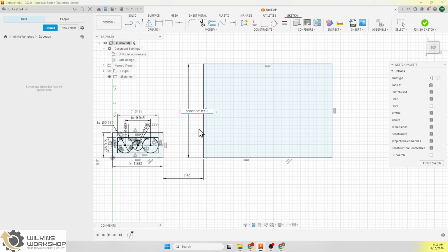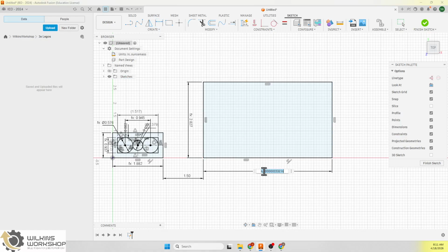All right, how tall should this be? Well, this should be Lego base times 3 minus 2 kerf. So that's how tall a 3 by should be. And then we go to this one. And this should be Lego base times 4 minus 2 kerf. So again, you only have air gaps on the outsides of the part. So that's why we're only taking off 2 of them. We don't put all the air gaps in the middle when we do this.